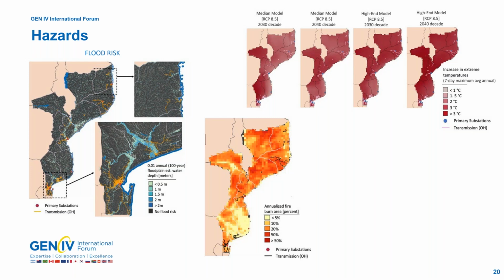That's less the case in a developing region like Madagascar, although that will be more US-like in the future. But they do have a direct impact on transmission infrastructure. In particular, when transmission lines get hot, the lines sag, and that can make it more likely that they'll interact with trees and biomass and cause fires. So that's something that you have to worry about. That physical lengthening of the lines also winds up reducing the transmission efficiency because you simply have to move the electricity over a longer area.